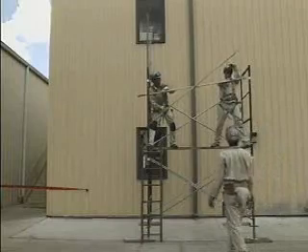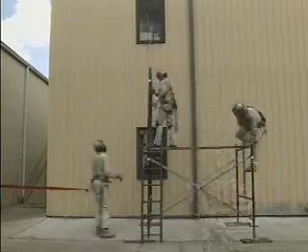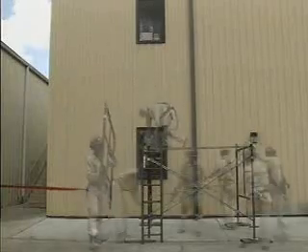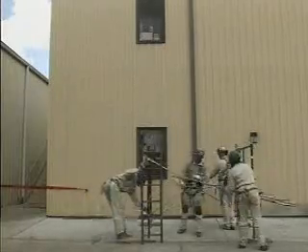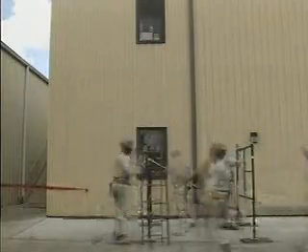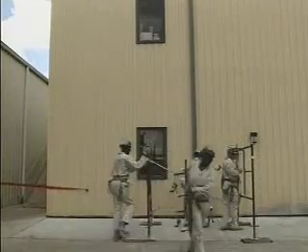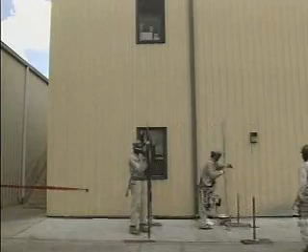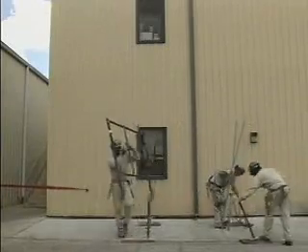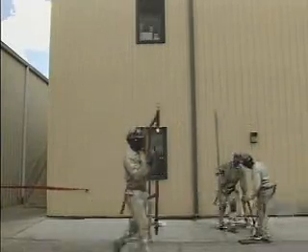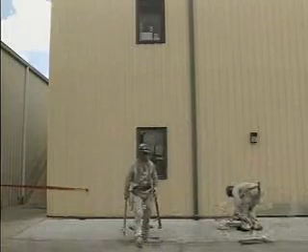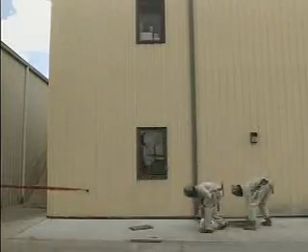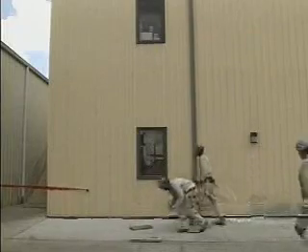Then the upper cross braces are taken off, and the upper end frames are lifted off of the lower end frames. The lower cross braces are removed next, along with the last section of ladder. Finally, the lower end frames are lifted off of the screw jacks and base plates. The screw jacks and base plates are then removed from the sills, and the remaining components are returned to their normal storage area.